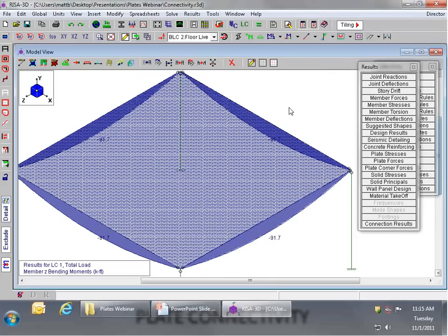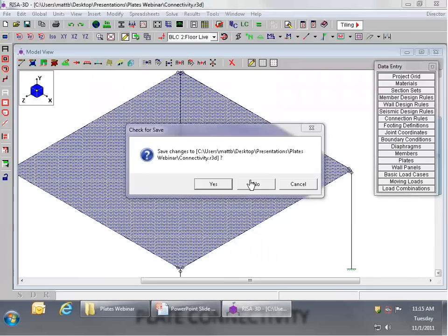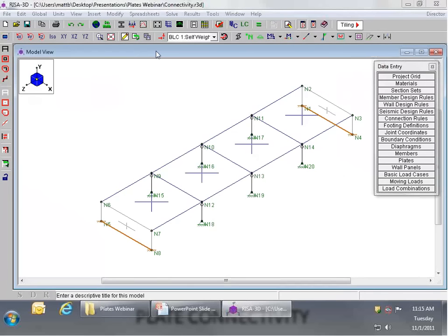I mentioned earlier that we're increasing the accuracy as we do each submesh, but there needs to be some sort of theoretical point at which you stop submeshing, because of course if we keep going with this, my computer's going to very quickly run out of memory. To show you how we do that, I'm going to pull up a separate model here. And this model that I have, I'm going to call my semi-rigid diaphragm model.